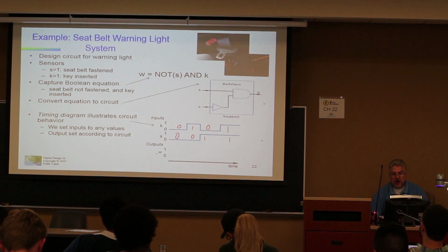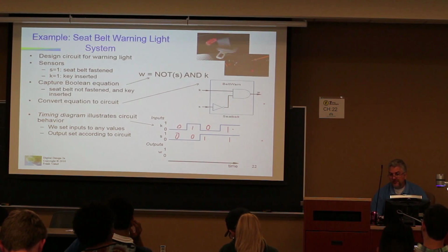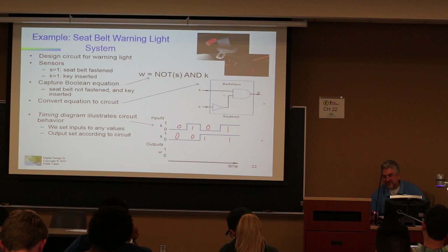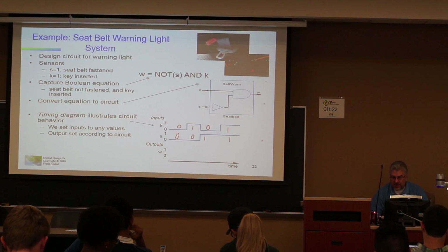What we would see for the outputs is, well, let's see. Since this is an AND gate at the end, of these four combinations, how many will result in a 1 for the output? It's an AND gate, right? 1, correct? We have only one situation when the input for the AND gate is 1 and this is 1.